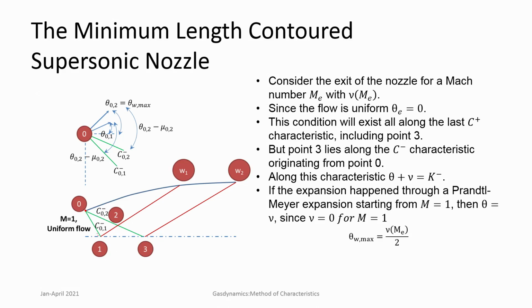Then for example, it is considered in this particular graph. So, we are only looking at the wave cancellation section. All the section over here is only wave cancellation. All the waves are produced at this particular point, which is a Prandtl-Meyer expansion. This is also the throat.